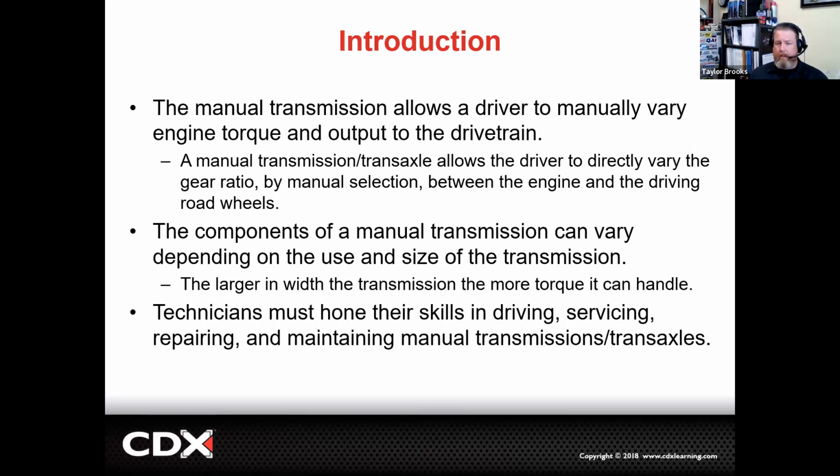When we look at what transmission is going to be in what vehicle, and why it's in that vehicle and what it's used for, we have to make sure that it can handle the torque which is going to be delivered by the engine. Now, the size of the transmission is often not always fully understood. When we talk about size of transmission, we're actually talking about the separation between the two shafts, between our input shaft and our counter shaft. The larger the spread between those two, the stronger the transmission will be, or the more torque it can handle.